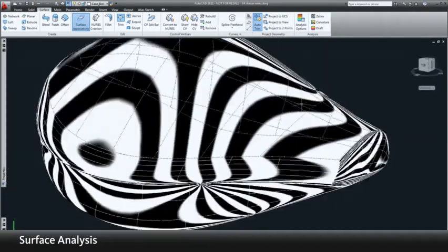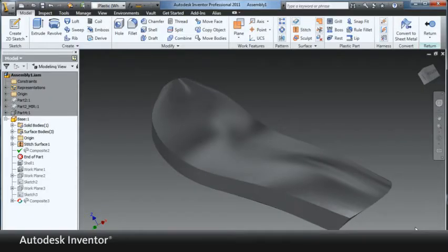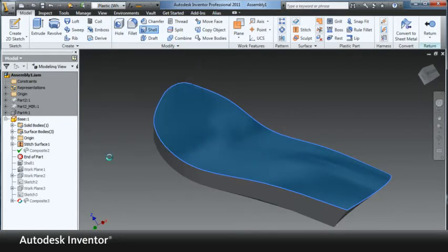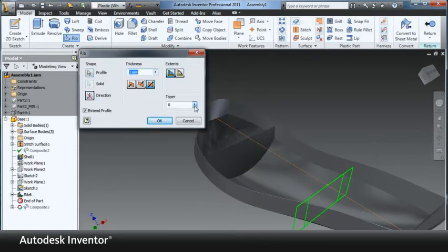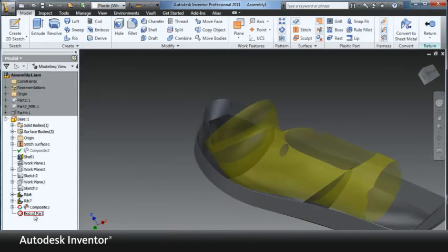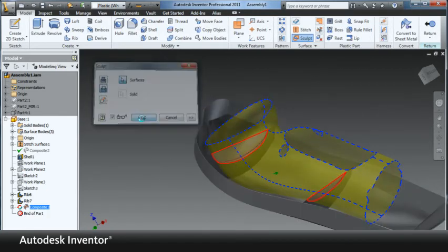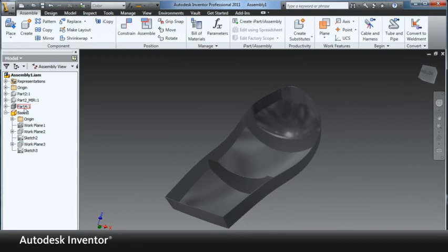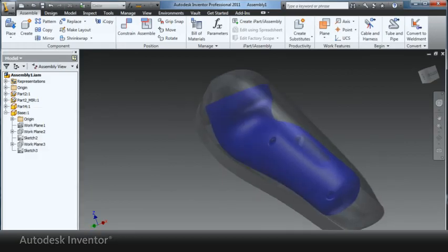Even though AutoCAD now offers unprecedented power for modeling, we all know that 3D is not enough, and that Inventor is the tool that can take you beyond 3D into digital prototyping. Simply open the DWG file in Inventor, and we can start adding details for fabrication. For example, we'll need to shell the geometry, add ribs as a structure, and add a series of details that will convert this conceptual design coming from AutoCAD into a real plastic part that can be produced. With AutoCAD 2011, you have a powerful yet familiar application that can unleash your creativity and communicate seamlessly with Autodesk Inventor for manufacturing.